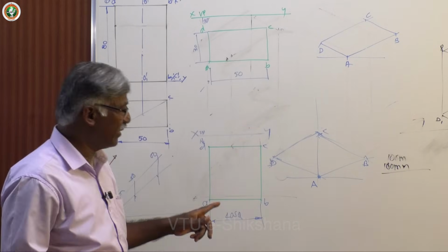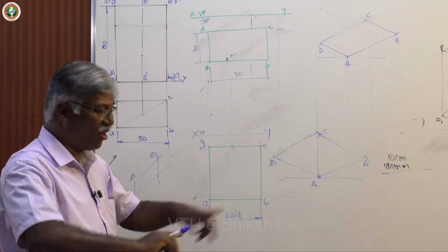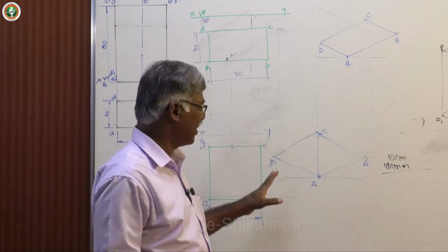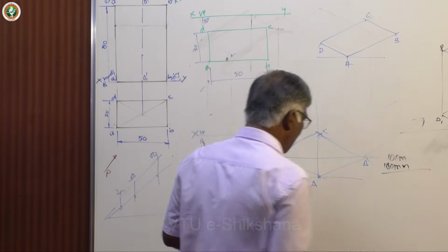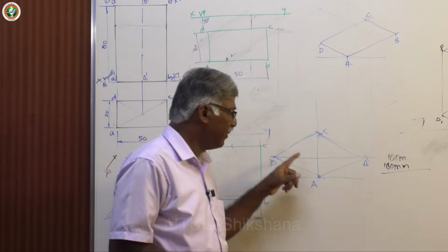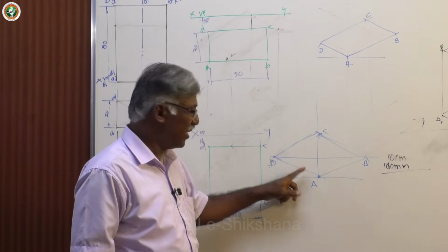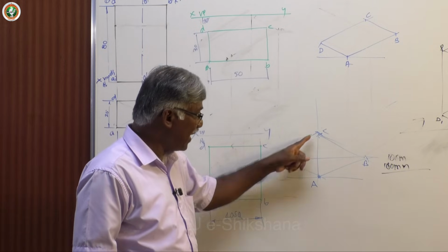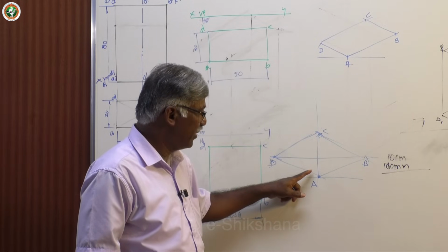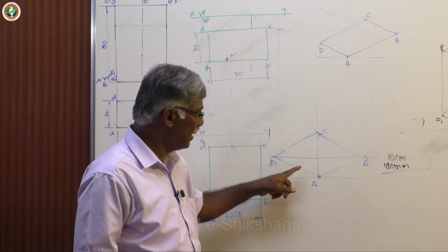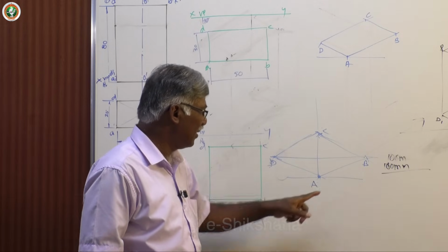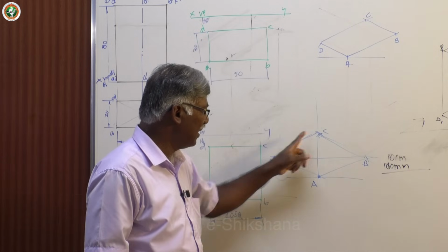But I have a better procedure than this, because here you have to draw a 30 degree line and see that these two are parallel, then join them, etc. I have a better method already. You might have learned it in your middle school and high school classes. Your teacher might have told you that the isometric projection of a square is a rhombus. The minor axis is this. The sides of the rhombus are always equal: AC equal to AB, AD, CD and CB.